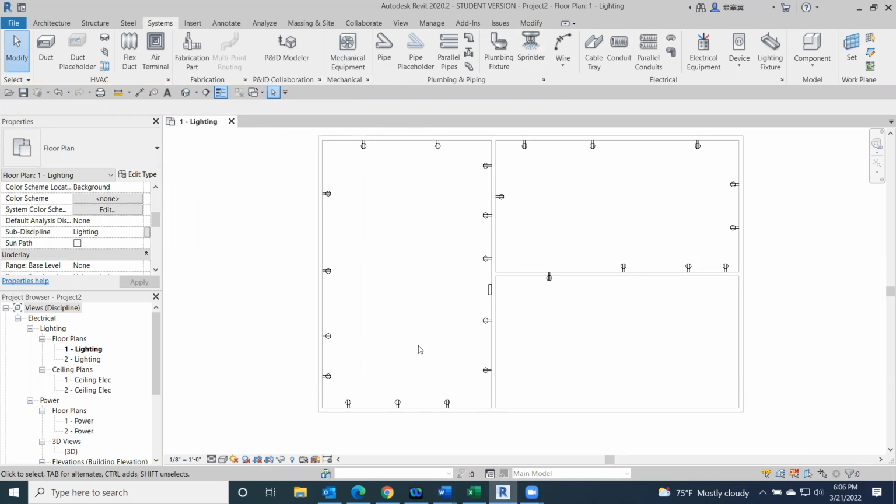So the confusing part is, okay, have I already put these guys in a circuit, or haven't I? And now we've got to go back and figure out which ones, if you're not paying attention at that time. This is part of the reason I think, especially when you're doing your bigger project, that it'll be easier if you do one room at a time and connect all those to one room. That way, as you line up your circuit panel, you'll be able to list that on your circuit box and your circuit breakers. You know, all these electrical outlets are in room 2, room 3, break room, whatever. So we do have those lined up.